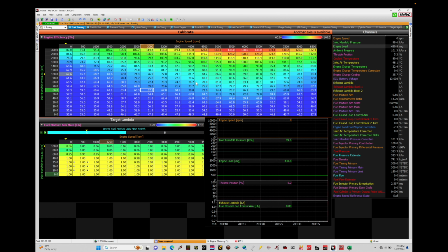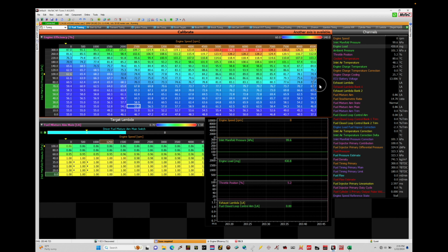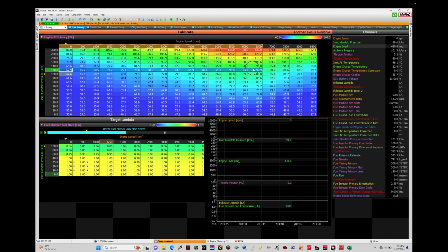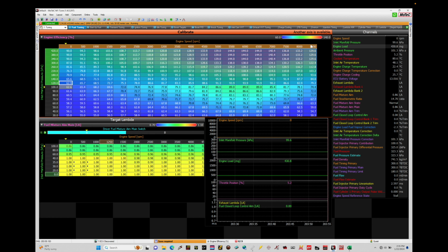Typical range of volumetric efficiency values: idle will be anywhere typically between 45 to about 60% VE. Part throttle anywhere between 60 to 80% VE. Full throttle, naturally aspirated, somewhere between 80 to 100% VE. And then with forced induction, we can find ourselves anywhere between 90 to about 160 maximum in our volumetric efficiency table values. So if we're finding that we're not in that...